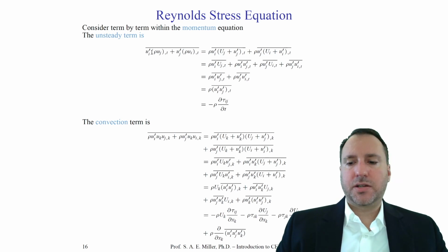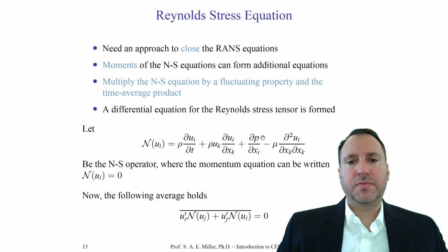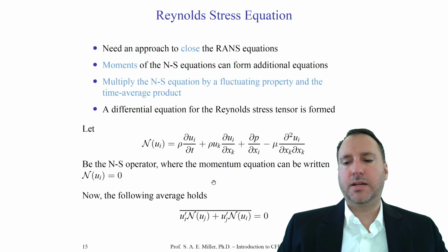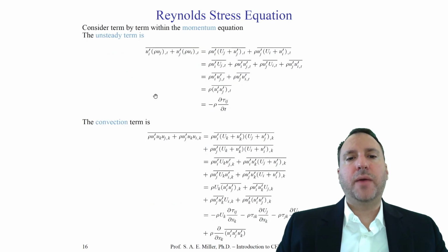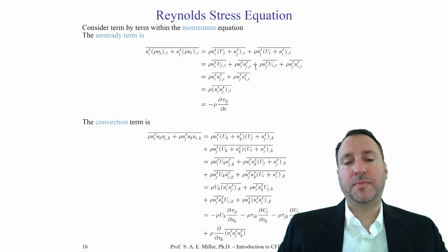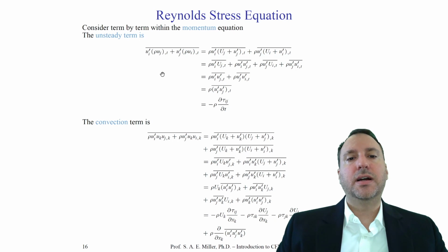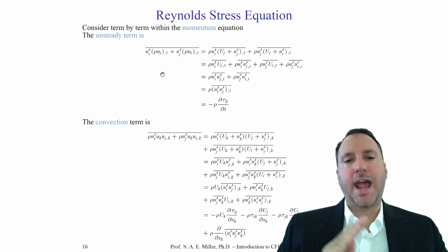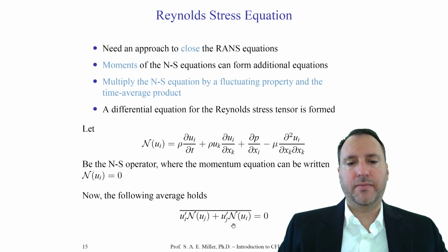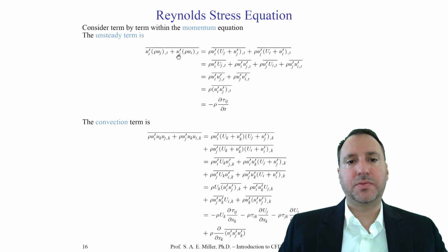What we're going to do is go term by term through this Reynolds stress tensor with this particular averaging technique of the moments, setting it equal to 0 by definition. We'll expand these out using all the rules we discussed in this class of averaging of 2 terms or 3 terms, expanding them out and setting terms to 0, which should be 0 because the averages of fluctuations are 0, etc. We can simplify these. And then we'll go term by term and add them all up to form this original average equation and set it to 0. That's what we'll do here.